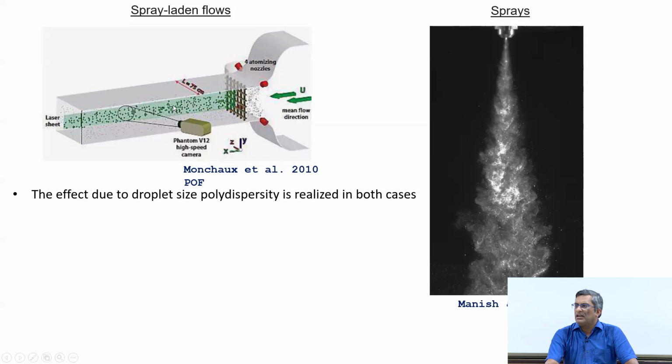So, this is a conventional way of generating turbulence in a wind tunnel. The large eddy length scales would scale with the size of these meshes. Then we can keep the mass flow rate the same and change the mesh size, or use different grids, to realize different turbulent intensity in the wind tunnel.